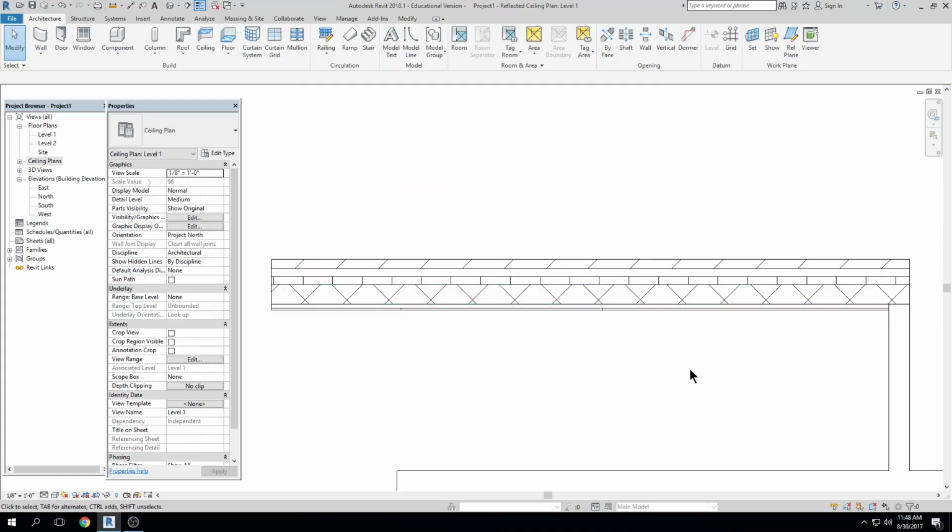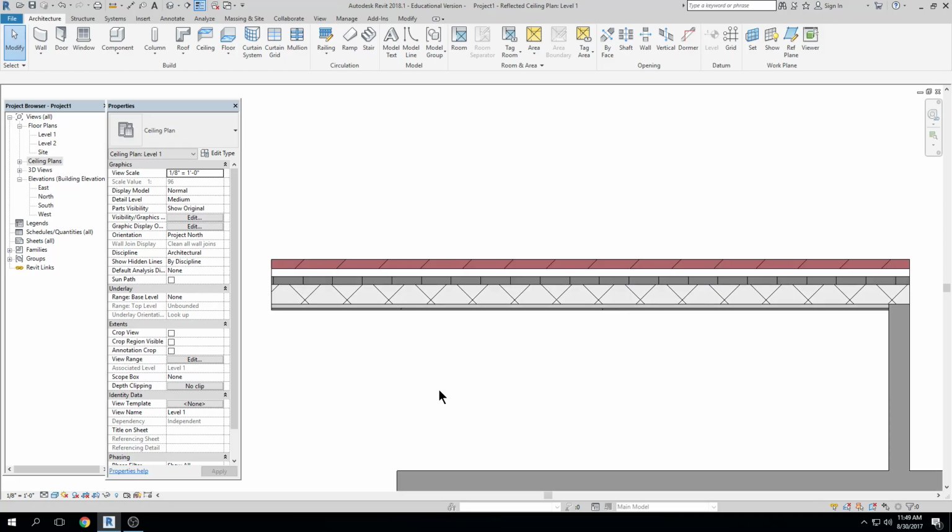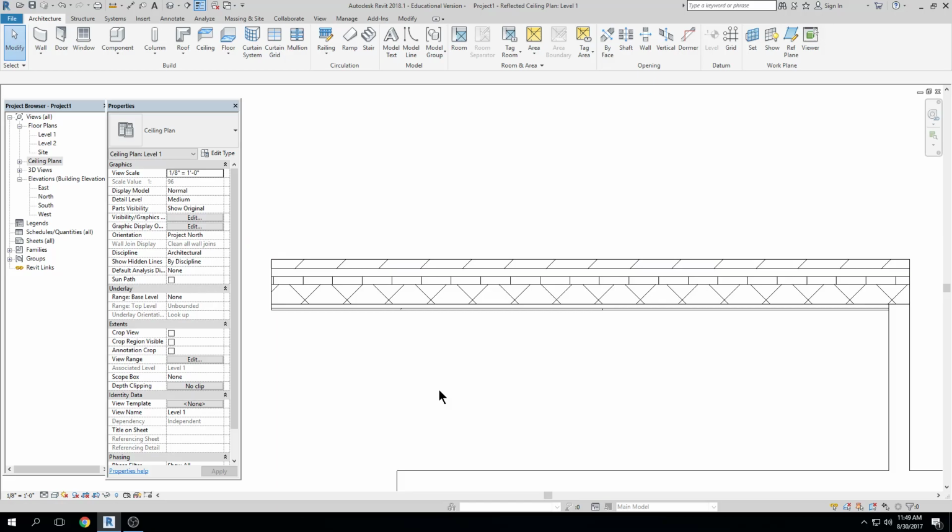And now those are showing up, all right? So that's what we go from, from coarse to medium, that's the kind of detail level we get. I'm in a hidden view. If I type shaded view, SD, it changes to color. HL, hidden line, okay?